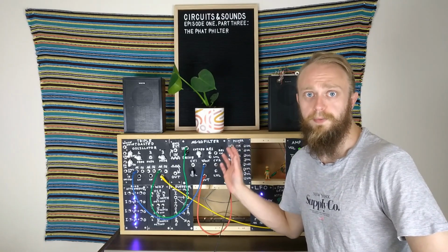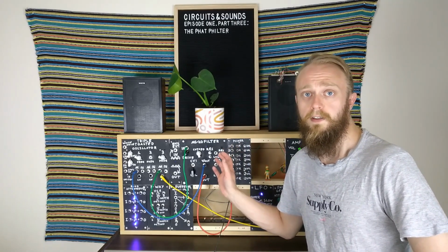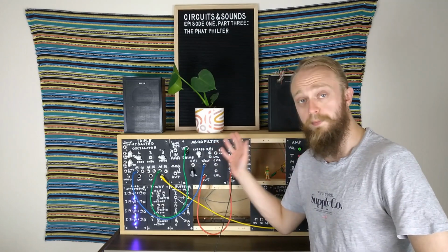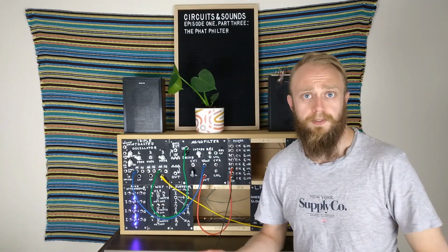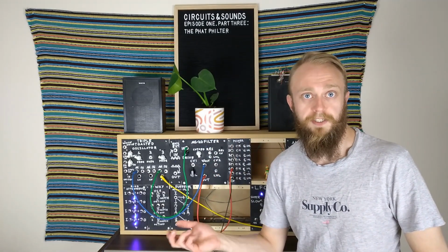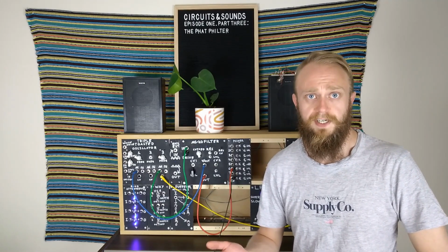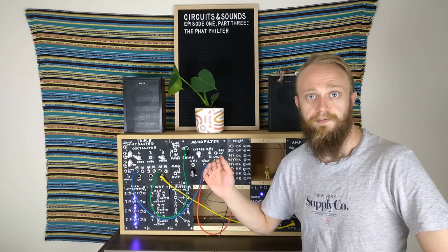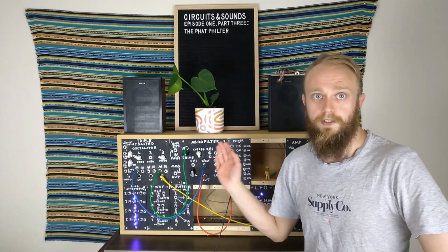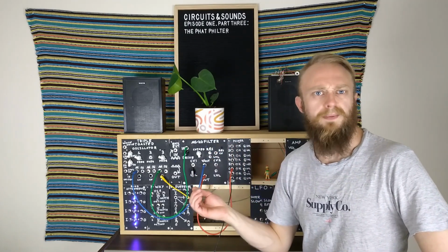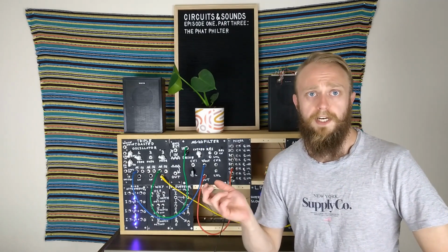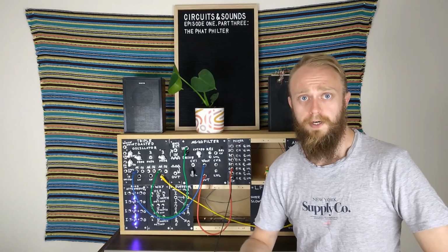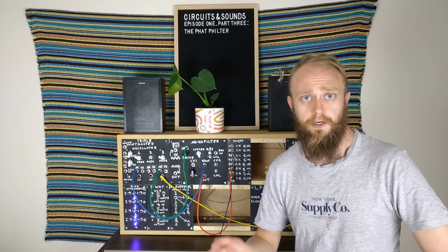So now that we have heard some of the sounds that this thing can make, I think it's time to have a look at the circuit behind the panel, which is based on the Korg MS-20 Filter clone by Rene Schmitz. So a few things to note before we start getting into it. The original circuit was designed for positive and minus 15 volts, but I've scaled it to my 0 to 12 volt standard, and it still seems to work just fine. So just remember that any ground connection you see goes to virtual ground, and any negative connection goes to actual